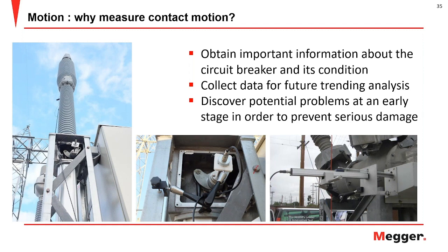A high voltage breaker is designed to interrupt short circuit current in a controlled manner, and this puts a great demand on the mechanical performance of all components in an interrupter chamber, as well as in the operating mechanism, and it has to operate at a specific speed in order to allow building up adequate pressure, for example, to allow for the cooling stream of air or oil or gas during the opening.